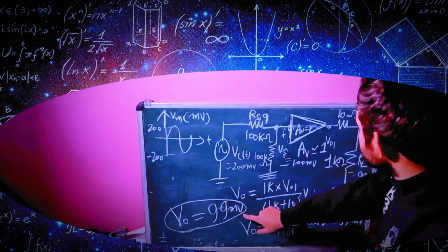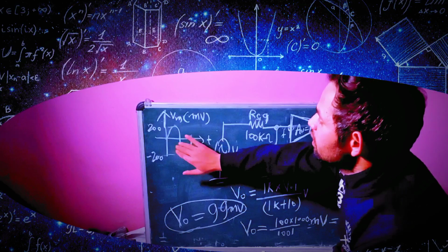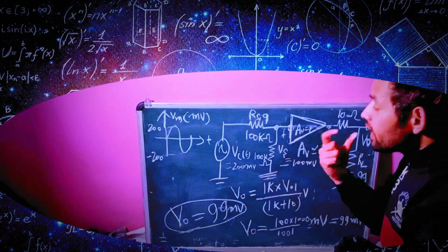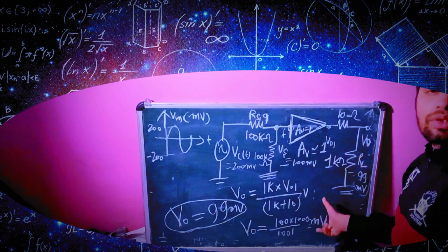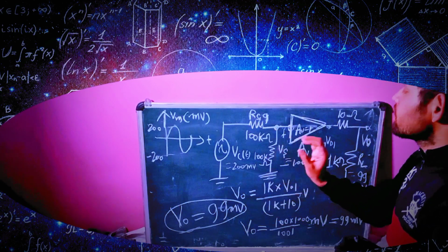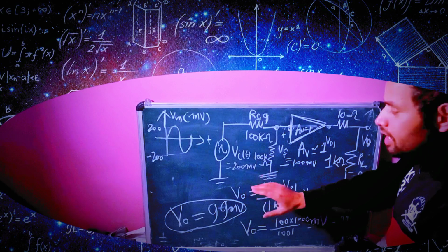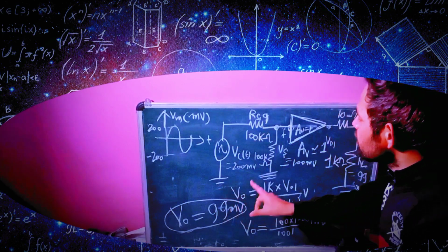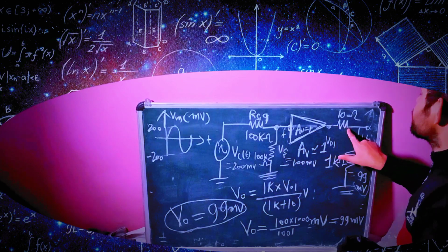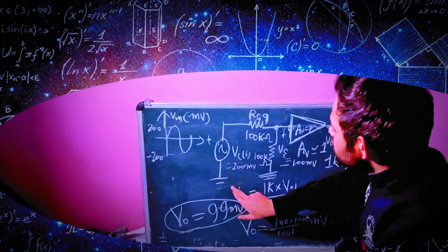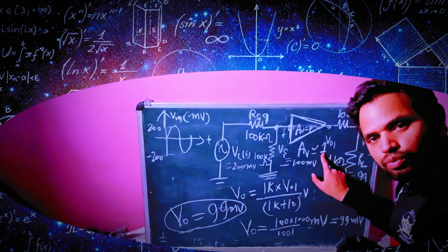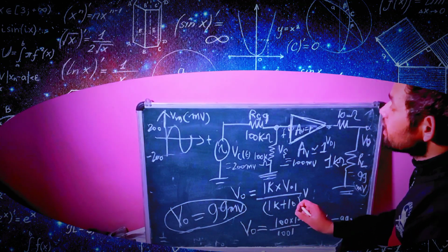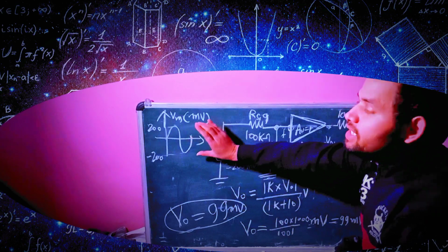Yes, you see here, 99 millivolt of signal that we are getting after applying this 200 millivolt, means we are able to hear the voice signal at the output across the load. Yes, which is a significant improvement in the signal. Okay, so with the help of this voltage follower, which is because of the common collector amplifier, whose input resistance is very large, output resistance is very low, and voltage gain is approximately equal to what? Unity, 1.